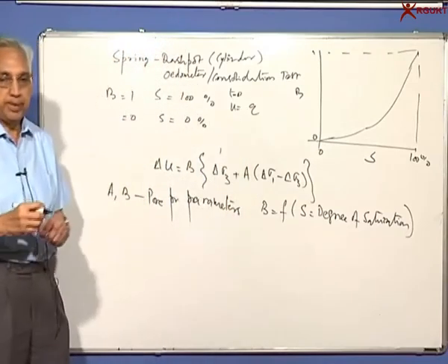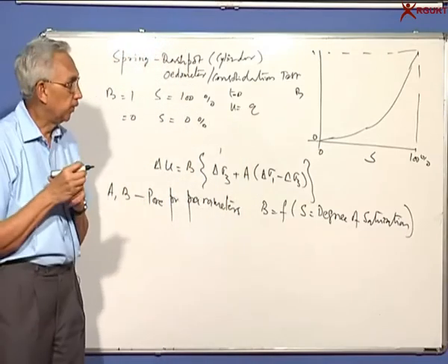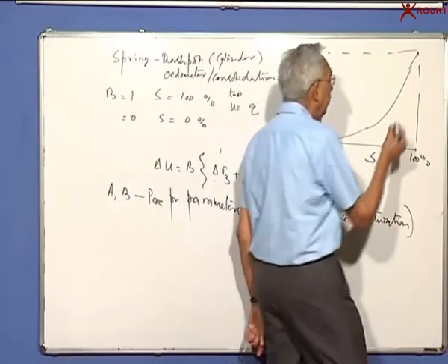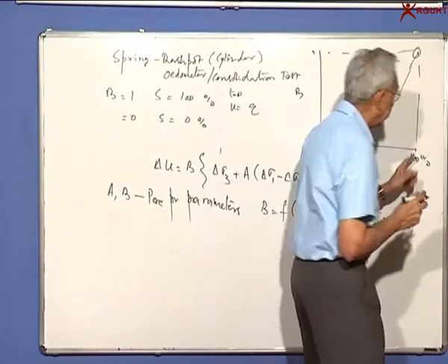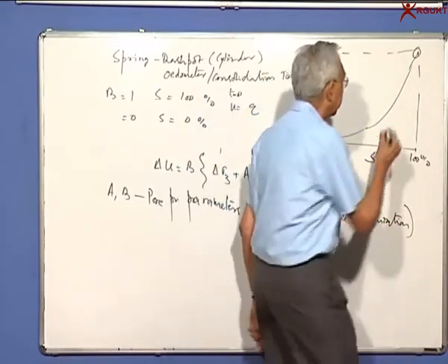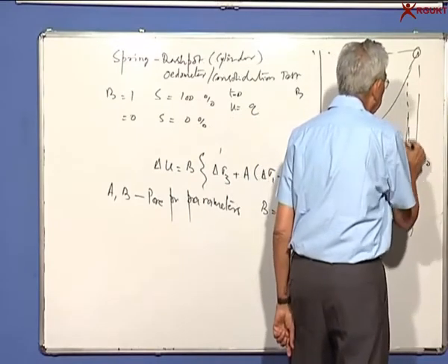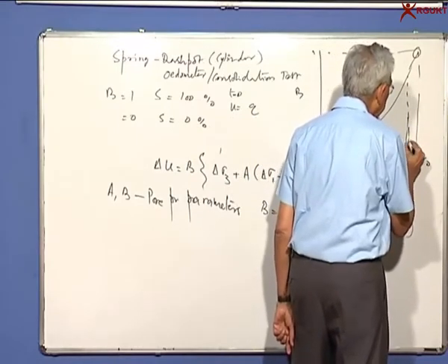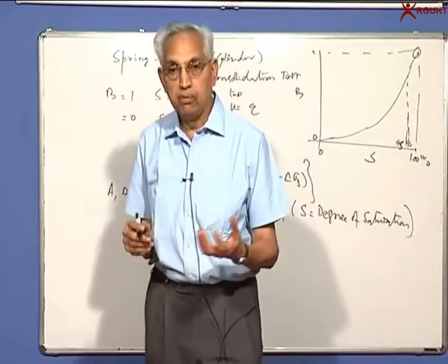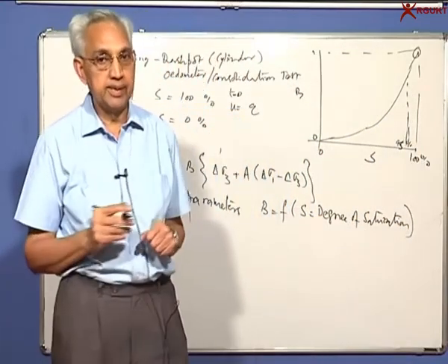Whatever load we put in goes into the pore fluid. It's exactly the same. The other interesting thing is, only when you reach full saturation does it become 100%. Even if the degree of saturation is 95%, the B value could be maybe not 1, but 0.9, 0.85, etc.